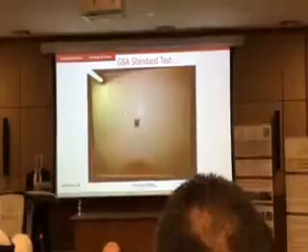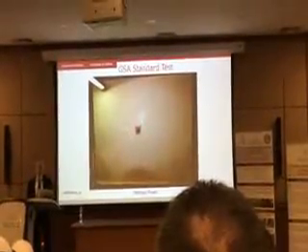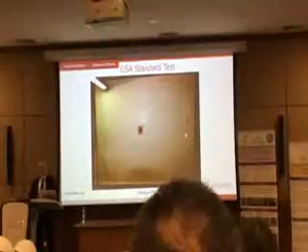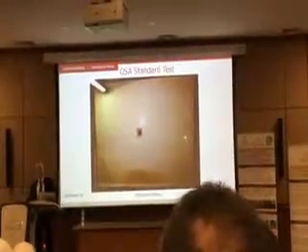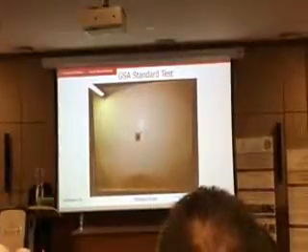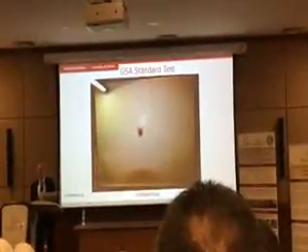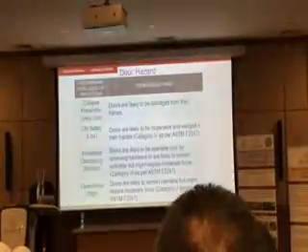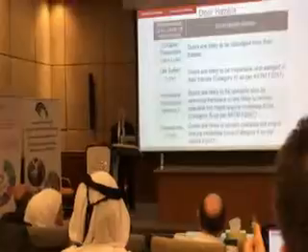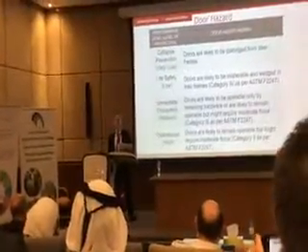You can see all the glass fragments marked, and we subsequently weigh them, and depending on GSA, if it's greater than so much weight, then it qualifies as hazardous glass. So it needed to be glazed with film, Securitas film. Okay?